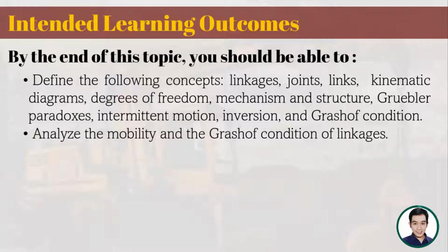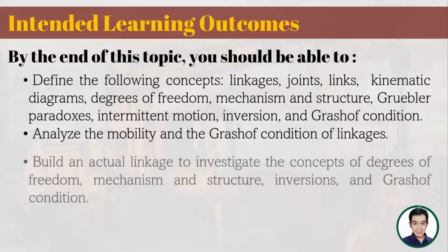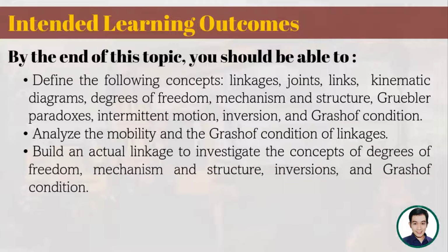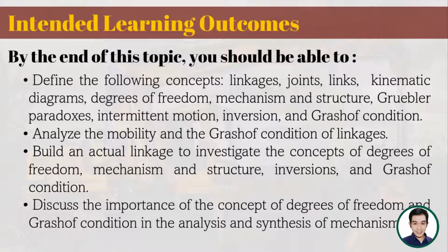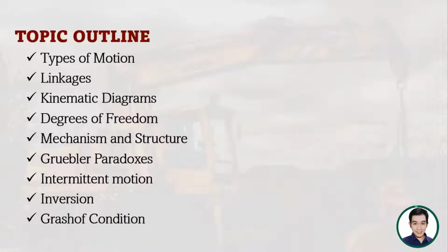Analyze the mobility and the Grashof condition of linkages. Build an actual linkage to investigate the concepts of degrees of freedom, mechanism and structure, inversions, and Grashof condition. Discuss the importance of the concept of degrees of freedom and Grashof condition in the analysis and synthesis of mechanism. This will be the outline of my discussion.